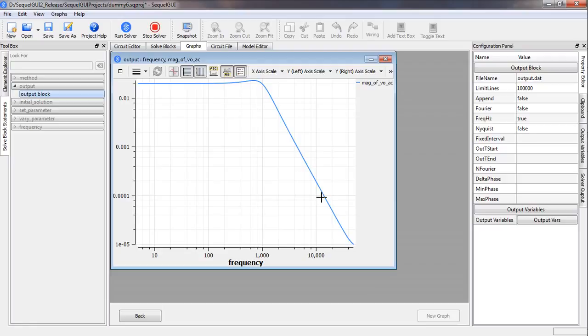That is, as we go 1 decade in frequency, we should go about 2 decades in the output magnitude, and that is indeed happening. So this filter does seem to perform as we would expect. What about the cutoff frequency? We expect it to be 1 kilohertz, so these two asymptotes should meet at 1 kilohertz, and that also seems to be happening.